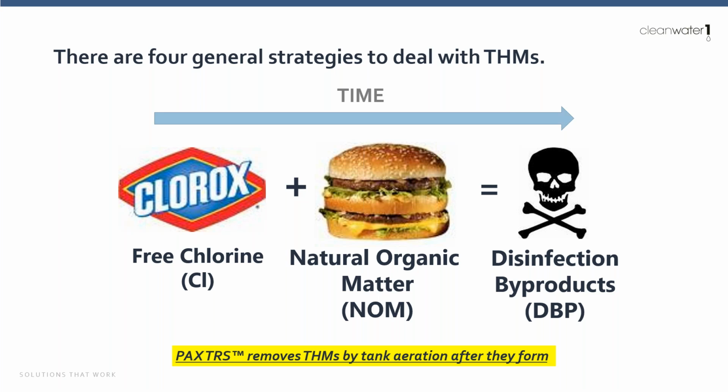Strategies there might include looping your dead ends. I know a lot of folks who are not filling their water storage tanks. There are some pretty significant drawbacks that come with that. We'll talk about that more in a bit. But yeah, really, optimizing your system hydraulics to reduce time in the pipes is something that folks are already working hard on. And frankly, most of that work's already been done. So if there's more to do there, by all means do it. But a lot of times there's just no more we can do to reduce detention time.